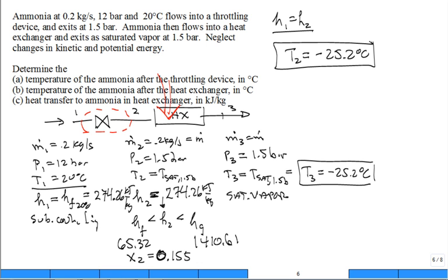That heat exchanger we would call an evaporator. Why? Because what's the fluid doing inside of it? 85% of it is going from liquid to vapor, evaporating or vaporizing. The 15% vapor is already vapor. It'll just come out. The rest is saturated vapor. But the 85% needs to be vaporized at that constant pressure.